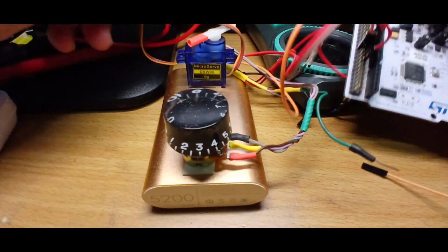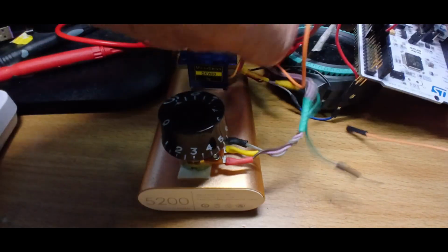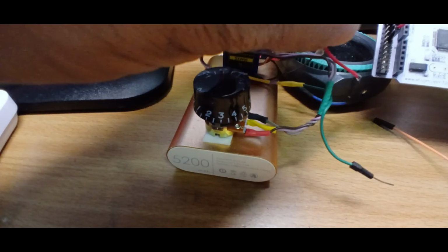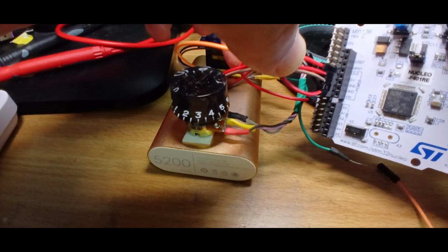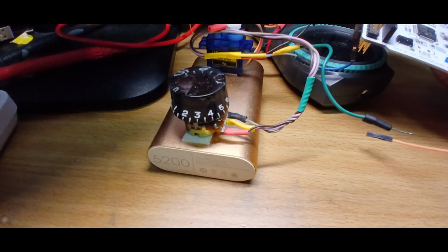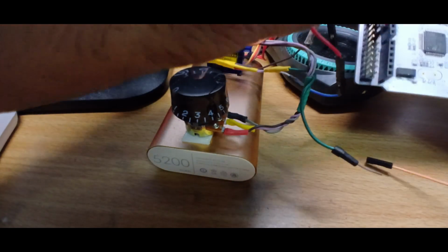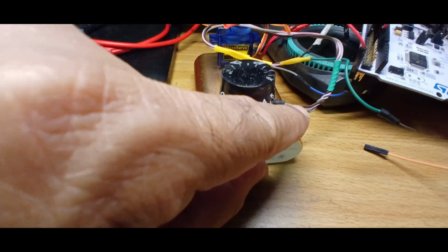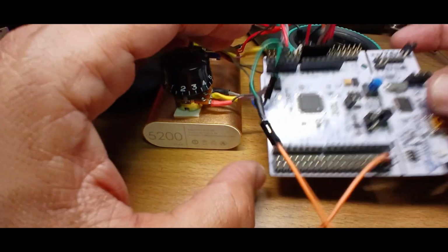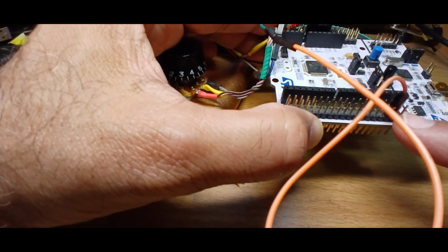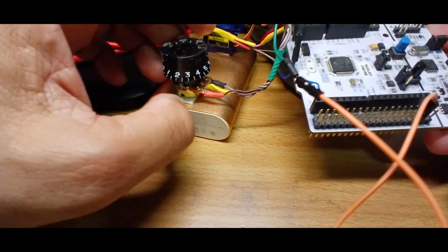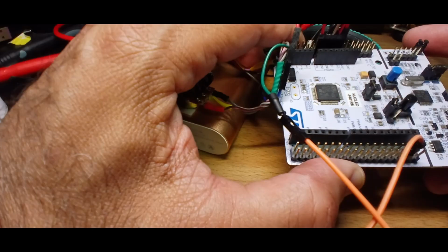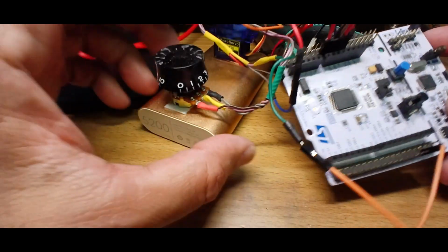Now you can see the potentiometer, 3 cables. This is our potentiometer and this is 10k ohm. First I connect here 3.3 volt. Okay, you can see from the Nucleo board. Then I connect the ground pin. You can see it is connected here to ground. Then the center pin, which is the potentiometer's center pin, is the signal line, the third line, 1, 2, 3, coming from the potentiometer center. It will go to PC5, that is ADC1 IN15. So these are our connections.